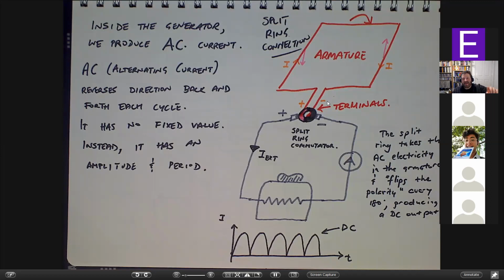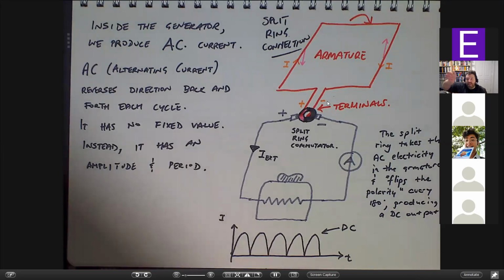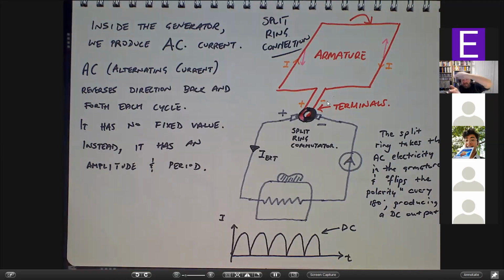You could have a generator driving a motor, but the problem is that because the current's always going in the same direction, you have the problem that we have with the DC motor, where it would get to that point there and then it would just go chick, chick, chick. Because once it gets to that point, we've got a force going this way, and we need something to flip the direction so that we then have a force pushing it down on the other side. So directly putting magnets on this will produce a motor, but a faulty motor.